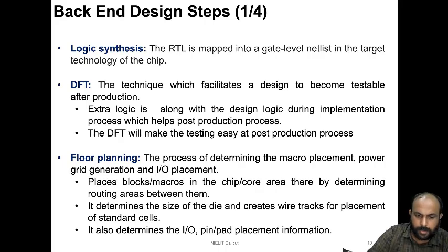So floor planning basically identifies where the blocks and macros should be placed on the chip. It also determines the routing areas between them, or where the connections should go in between them. It determines the size of the die and creates wire tracks for placement of standard cells. It determines the input-output pin pad placement information as well. So these are the functions floor planning should do.